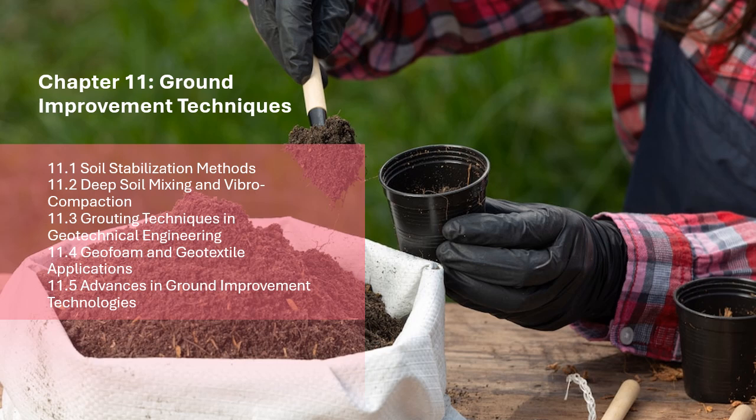1.3.4 Advantages of grouting techniques. Increased strength and stability. Grouting improves the strength of weak soils, making them more stable and capable of supporting heavier loads. Reduced permeability. Grouting helps to decrease the permeability of soil, preventing the infiltration of water into structures or foundations. Cost-effective. Grouting is often a more cost-effective solution than other methods of ground improvement, especially for large areas or sites with complex soil